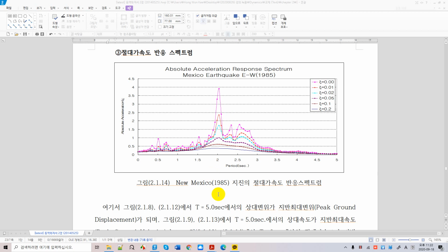Because of the soil conditions underneath the buildings in Mexico City. It is very thick fill soil, so the earthquake propagates through the thick soils and creates a 2-second dominant period, so it is going to cause a big resonance response for buildings of around 20 stories, right here at 2, right?